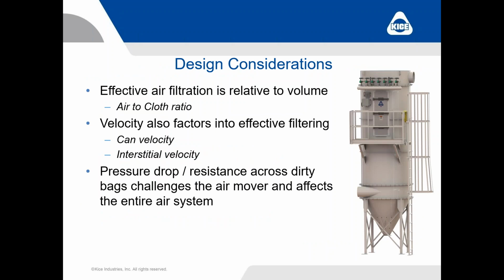So let's talk about design considerations. What do we think about as an equipment manufacturer, as a system designer? What do we think about from a sizing and engineering standpoint to size a baghouse for you? We don't just have a small, medium, and large baghouse and decide which one fits the best. We take a lot of things into consideration. The most common, the most visible, and the easiest to speak about are air-to-cloth ratio, the velocity of the air and the particulate inside of the baghouse, and then, of course, what I just mentioned, pressure drop across the filter.